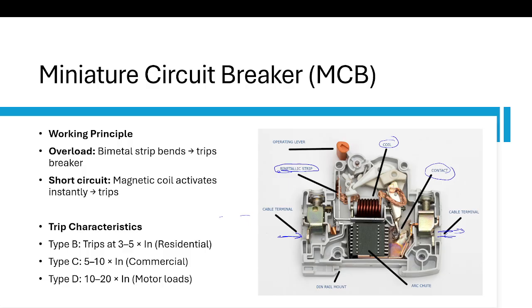So what is the importance of MCB? It prevents damage to contacts, improves safety, increases breaker life, and after clearing the fault, it can also be reset. You can see this is the operating plunger, the operating lever. This gets tripped. If this is in normal condition, it comes this way. Just need to reset, so we can use it again.